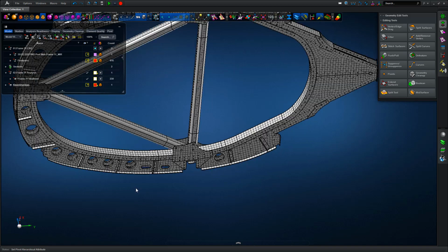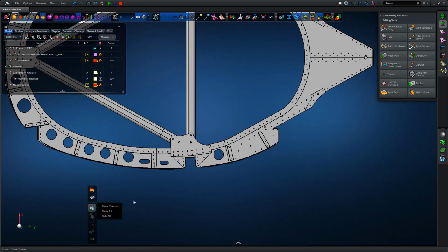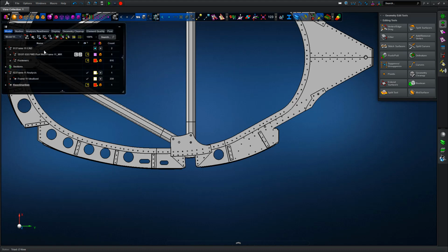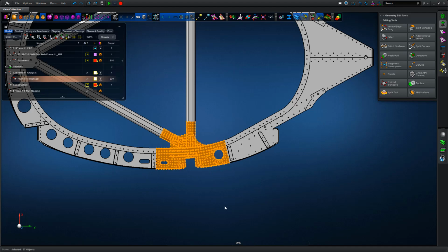So once we've got the region cut, we're going to create a new subassembly which we're going to define as our coarse model representation for the resultant analysis definition. So we're calling this frame 11 region of interest coarse, and the reason for doing this will become clearer in a moment. And then we're going to select as a screen pick all of those entities.